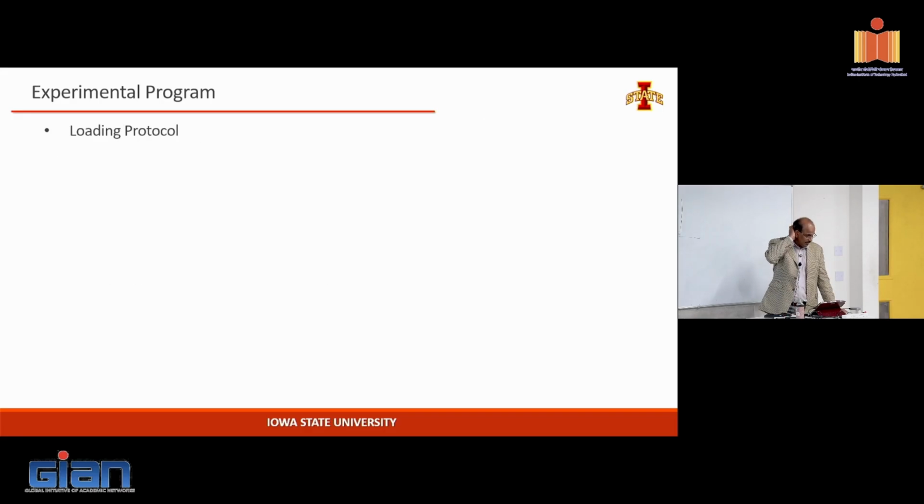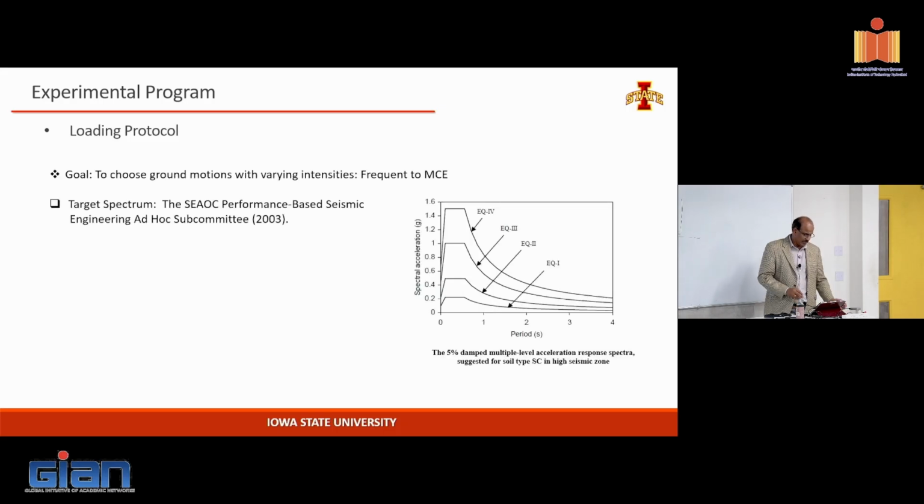Okay, so I want to spend a little bit of time on the loading protocol. It's something important that you understand if you are a student, a grad student doing graduate work. When you design these structures, you want to go through an evaluation in a dynamic manner. The question is, do you use recorded earthquakes? Do you use spectrum compatible earthquakes? Do you use simulated earthquakes, simulated loads? For example, I assume in India, especially if you come to the South, you probably don't have significant recorded large earthquakes, so which one to use?